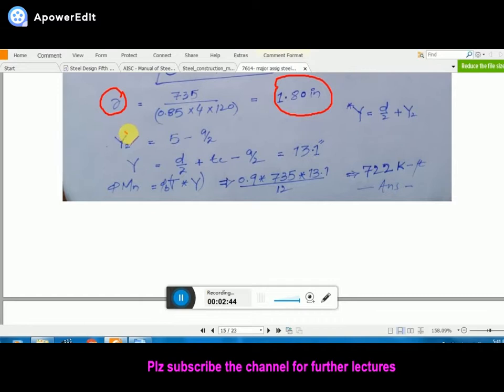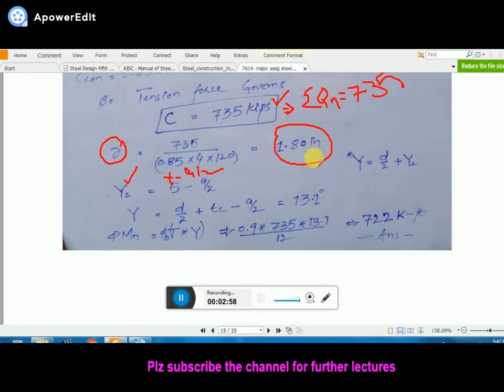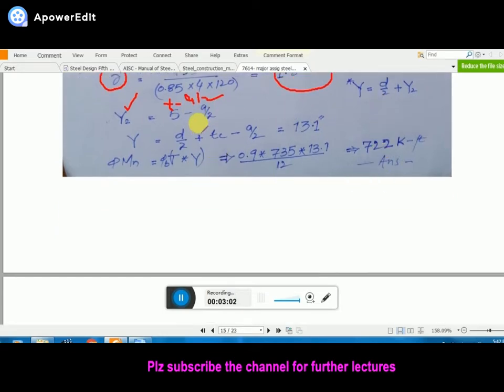We use y2, which is the concrete thickness minus a over 2, and this y2 comes out to be, I think, 5 minus a over 2. I didn't write it, but you must make sure what the value of y2 is. Clear? This is the lever arm, and this is 13.1.